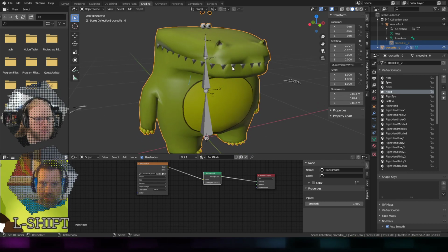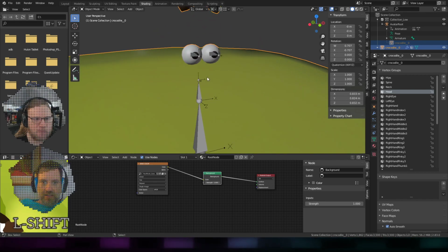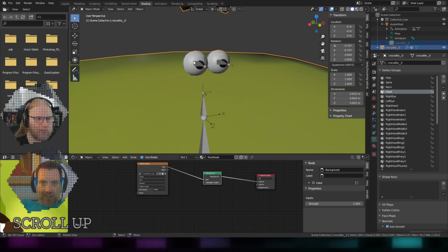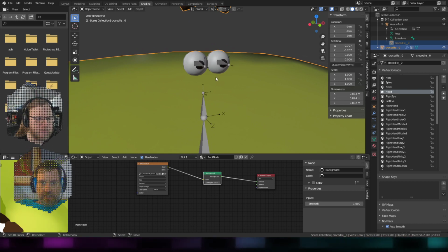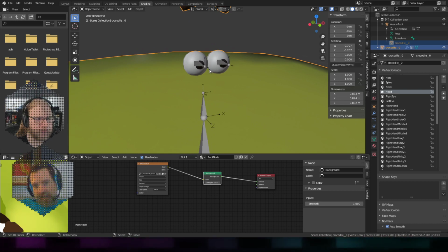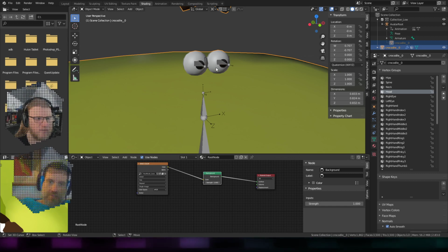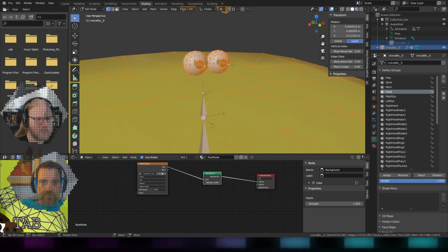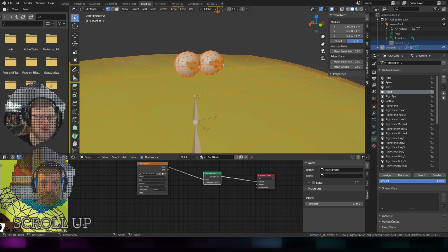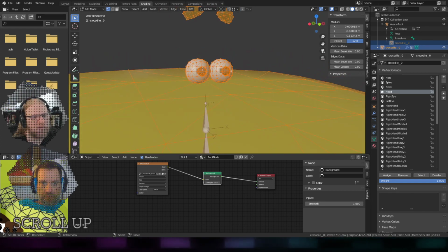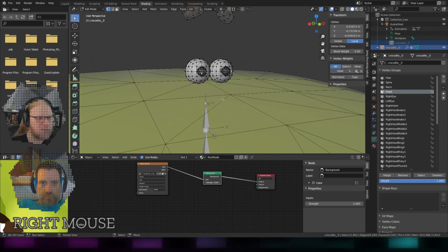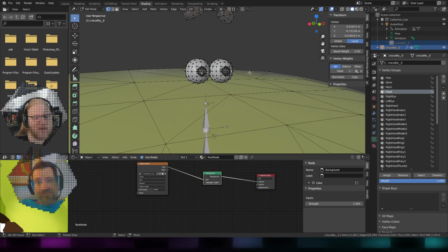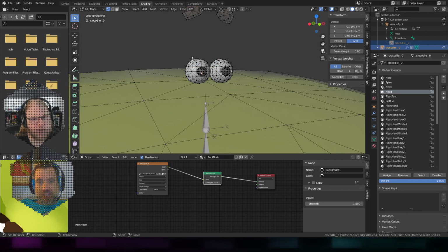So that's cool. And then the other thing I'll do is assign the eyes not to the hips or the head, but to the actual eye bones, and they'll move with the head since the head bone moves the eye bones. That's the reason they're in a hierarchy. The hierarchy does affect everything downstream, but weighting the different pieces separately is going to allow you to control them differently.